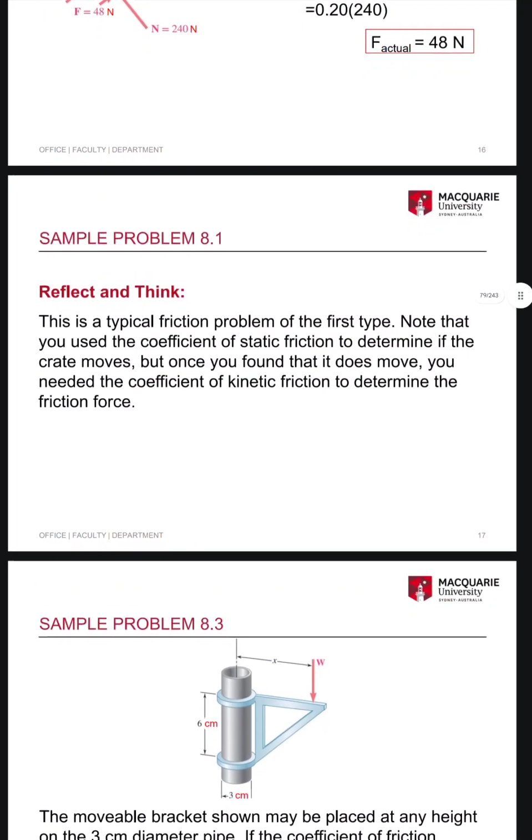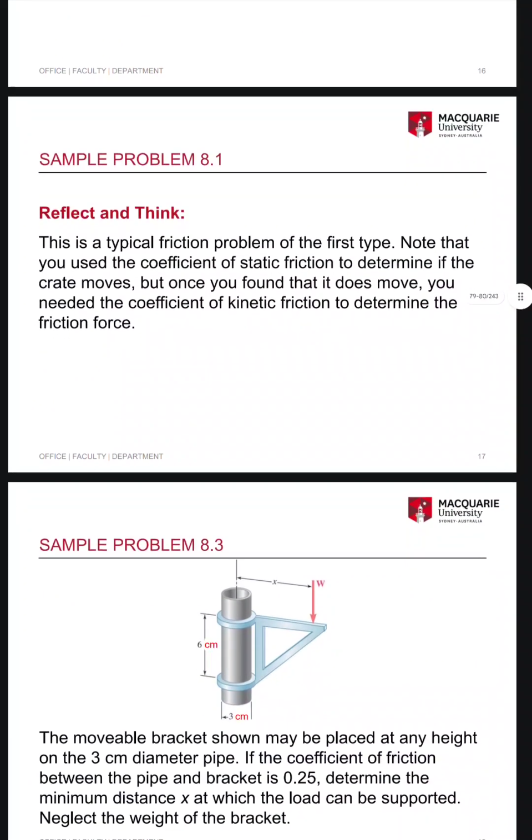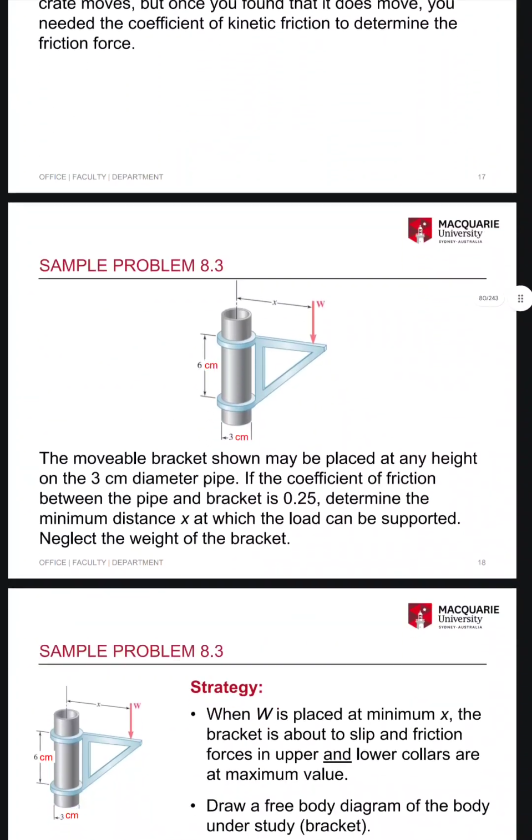Note that you use the coefficient of static friction to determine if the crate moves, but once you found that it does move, you need the coefficient of kinetic friction to determine the friction force.